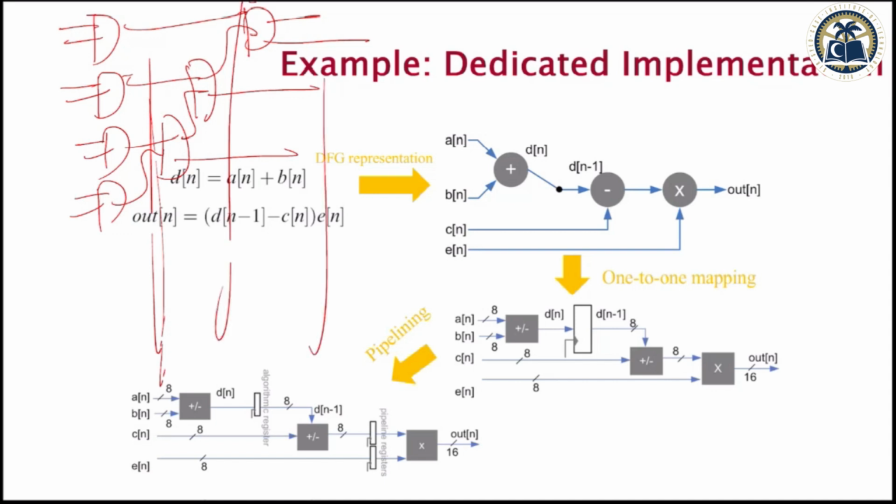The only bad thing about registers is that if you are trying to make your critical path faster, you have to find all the paths that are running parallel to the critical path. So you have to cut the circuit vertically and put registers everywhere so that they are synchronized, and every clock it is getting new data. After every 5 clock cycles it gets the result of the first sorting, and after that every clock it is getting the result of a sorting.